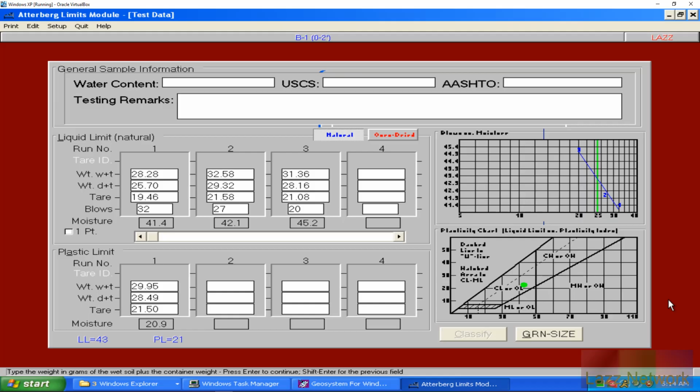And washing it is exactly as you think it is. It's running water over a sieve, and you're washing all the fine particles through. That's one part of classifying your sample, the bare bone basic to classify a sample. So if you want to say if there is silts or clays or anything of that type, you have to do a wash, basically.